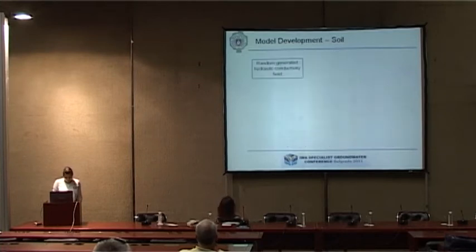Now, how we do the hydraulic conductivity field: we take the mean and the standard deviation of the saturated hydraulic conductivity and generate this random field. The parameter P here is a random number that is the probability that the value of saturated hydraulic conductivity is K.